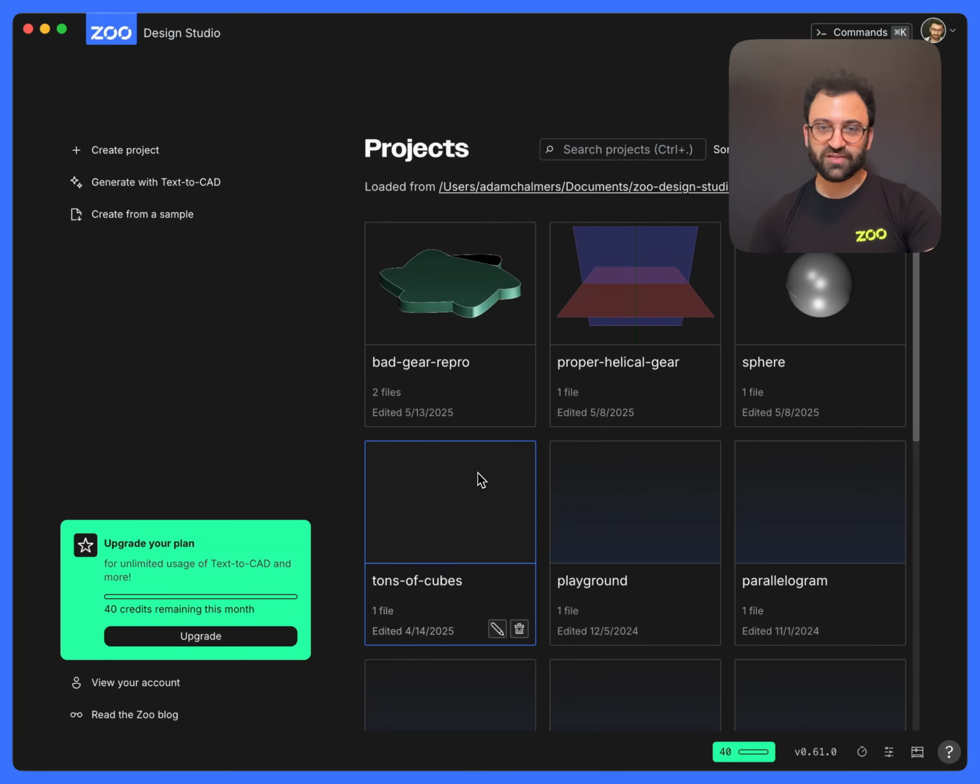So you can use KCL to code up mechanical engineering parts like clamps or flanges and really anything you can imagine. Anything you can do in a point-and-click CAD interface, you can do in KCL too. So today I want to demo how KCL works for you. I want to get you into your first KCL program.